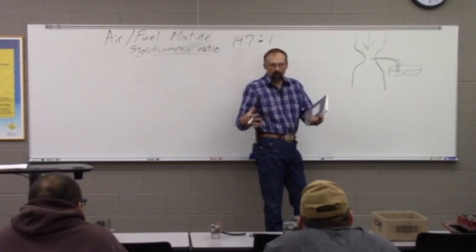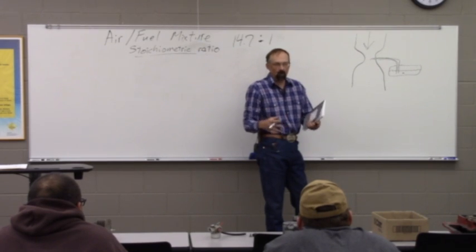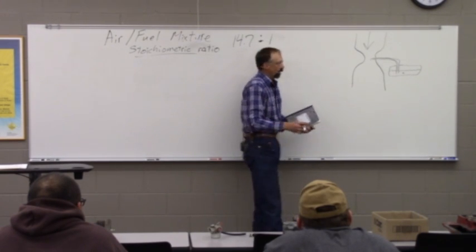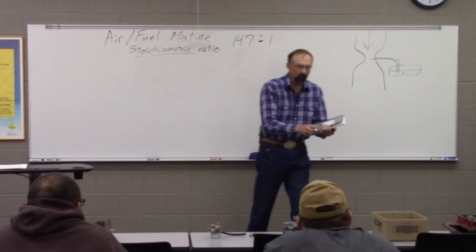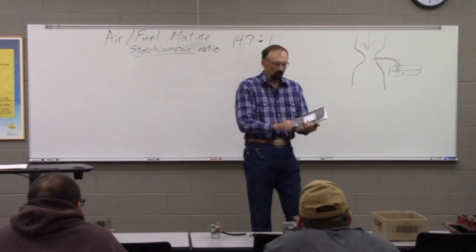And for the combustion process to happen in the cylinder, it really does not work well when the fuel is still a liquid. And it worked really well once we vaporize that fuel. So there again, we're not working with liquid oxygen and liquid fuel when we're making that explosion. We're working with vapor oxygen and vapor fuel.